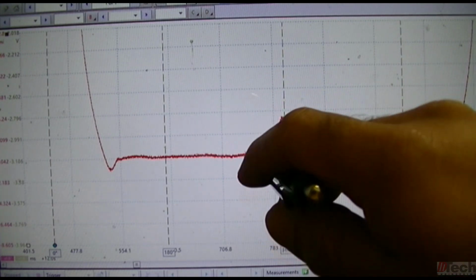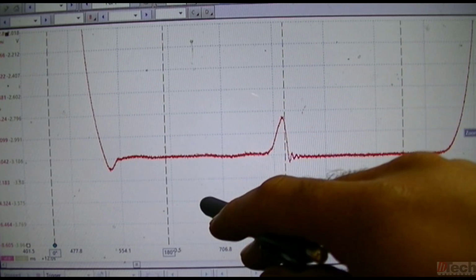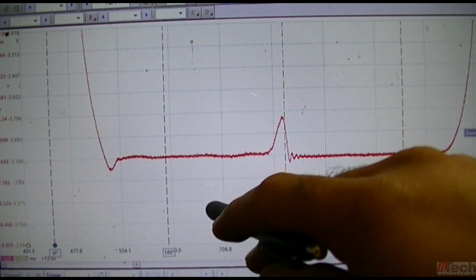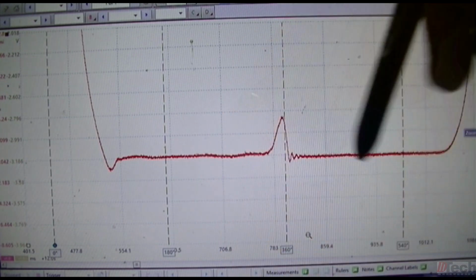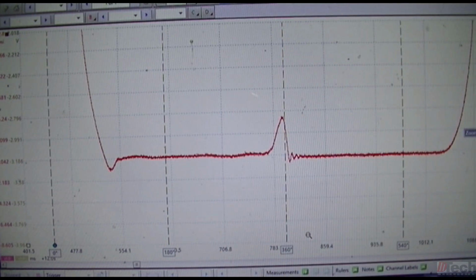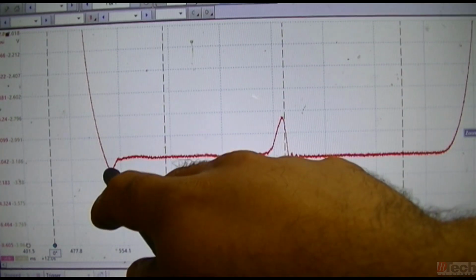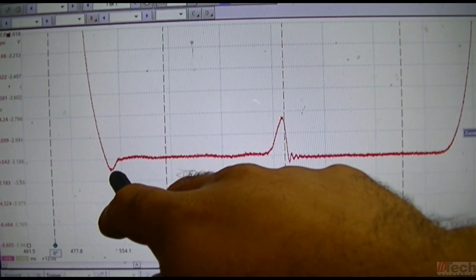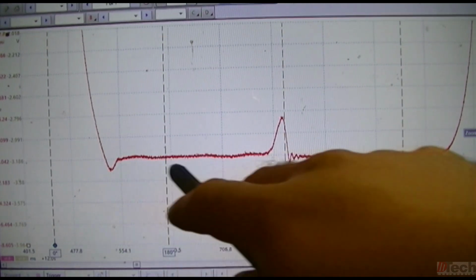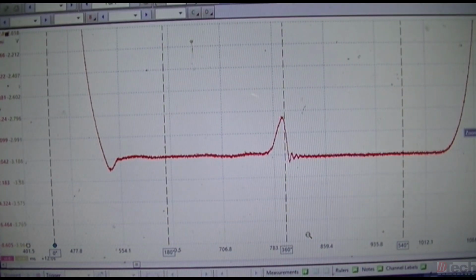That is most likely what's going on here, being that the code is supposedly reading that it is too advanced. So one quick thing that we can do is take a measurement of this point when the exhaust valve opens and when it closes and compare them bank to bank.